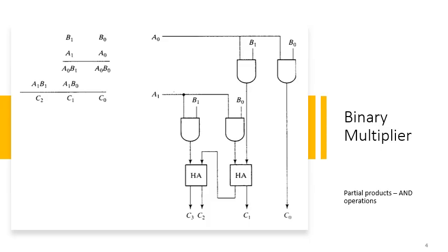Now coming to the binary multiplier circuit, it has the capability to multiply two binary numbers. We'll discuss an example that multiplies two binary numbers of 2 bits each. The basic principle of multiplication is the same as with decimal numbers. In this example, A and B are the two numbers with their respective binary bits. B0 and B1 are the binary bits for the number B, and A0 and A1 are the binary bits for the number A.